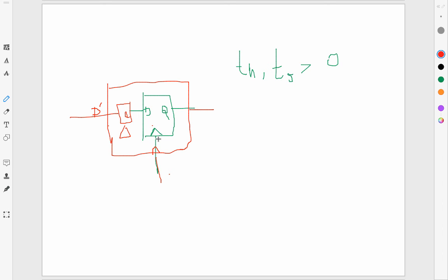Now, normally signals come from another circuit, a preceding gate, and therefore I can control very well whether I'm meeting the setup time or hold time, as we talked about. Can you think of some setting where it would be essentially impossible to meet setup and hold time requirements? Now, remember, it is not about changing faster, it's about when they change. So think about under what circumstances you really don't have any control over when they change.